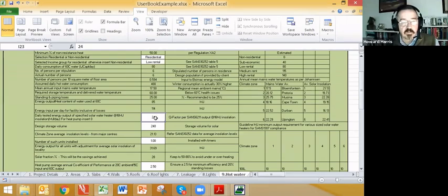Yes, if your collector plate or your vacuum tube system is suboptimally orientated, let's say if it faces either east or, preferably, towards the west, the possibility of boosting that does exist, but as Graham says, one needs to be very careful about that. Particularly in Cape Town, where you have extremes of very high solar insolation in summer versus low insolation levels in winter. We only have one such unit installed in this particular house.